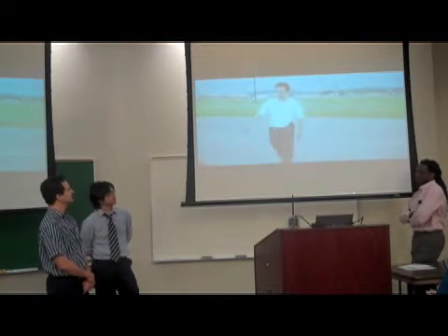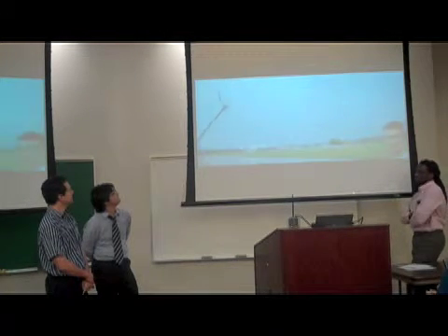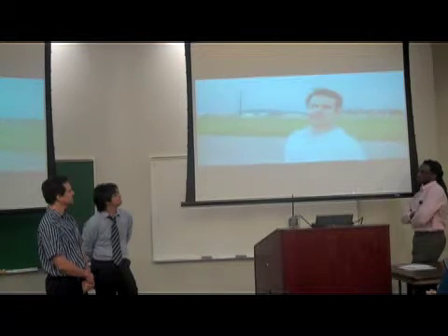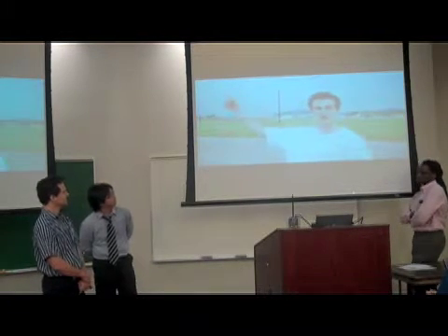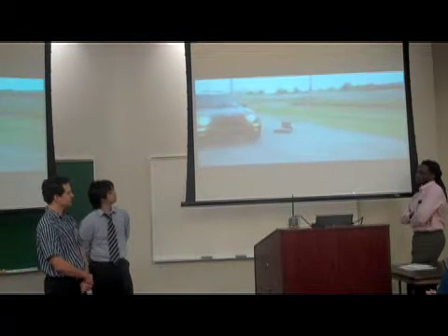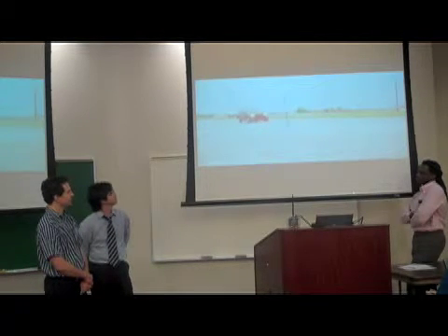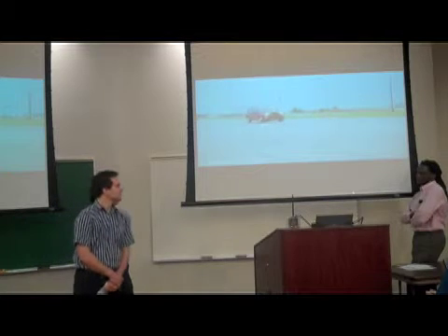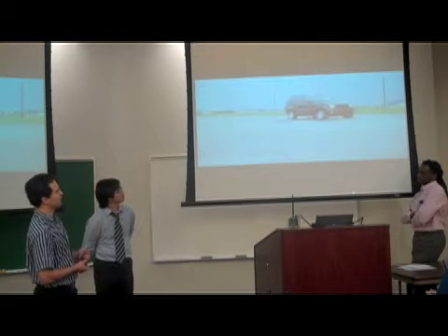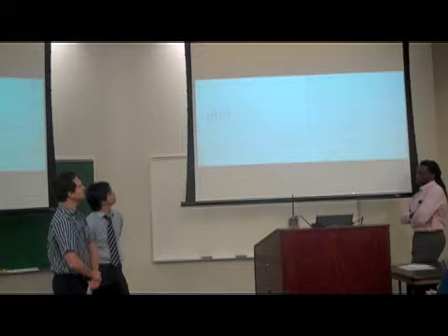Then shortly over here off to the side of our road is our gateway, which is mounted up here on this tripod. The gateway receives the information from the sensors and calculates the speed and the size of the vehicle, then transmits that via Zigbee radio over to our computer, which is set up over here with a Zigbee receiver to receive that. In a minute we'll show some comparisons with a radar gun, and you'll see the radar readout on the right-hand side of the screen and our readout on the left-hand side of the screen.